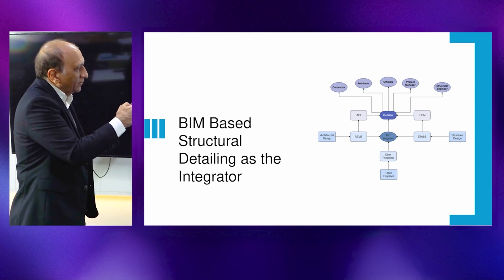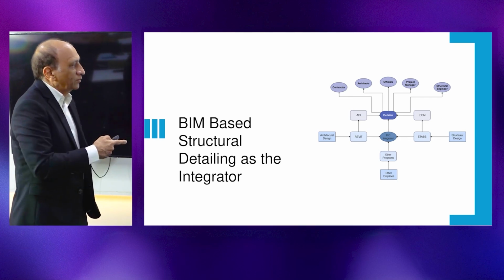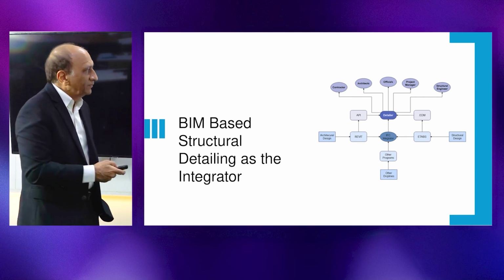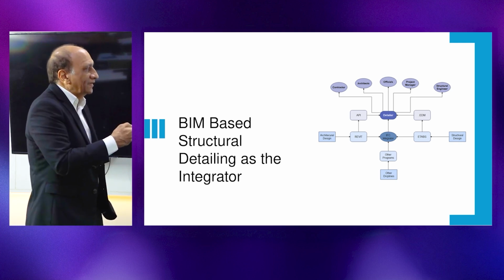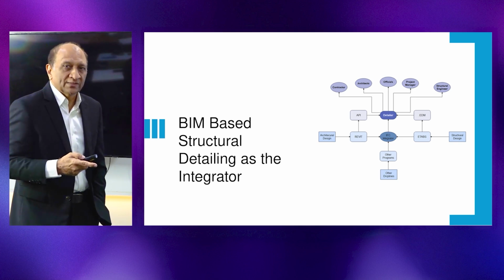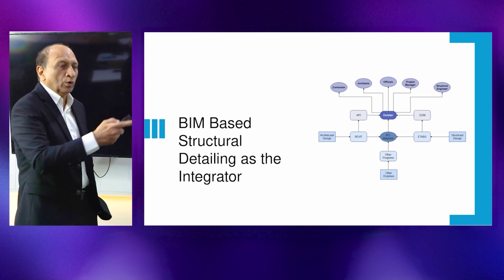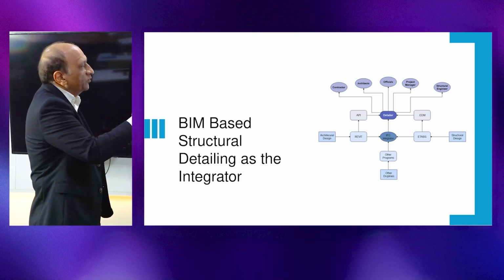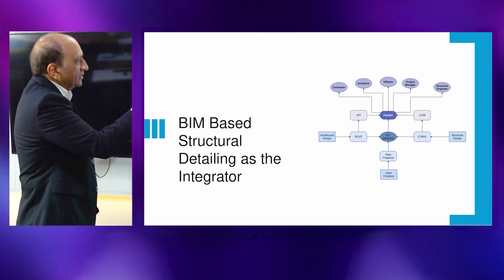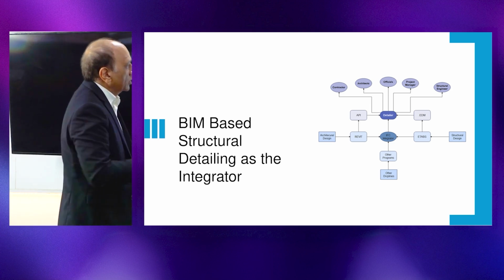We can have the building architectural design, create a Revit model, and from there use an IFC converter and do the detailing right away without going to the structural design at this point, because we know typical detailing rules already from codes and practice. And then this information can go to contractors, architects, officials, project managers, or structural engineers.